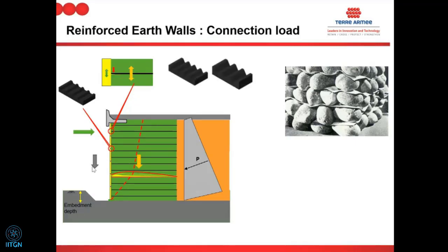So if you have a very tall structure, say 20 meters, which is very rare, but I want to highlight this because you are going to be on the field someday or the other. Please remember that the bearing pad is not a standard element, like the commonly known 20 millimeter thick pad of a certain dimension. It is not like that. As the wall height increases, and as you have different kinds of soil, the dimensions of the bearing pads are also different. And especially when it goes beyond 15 meters.